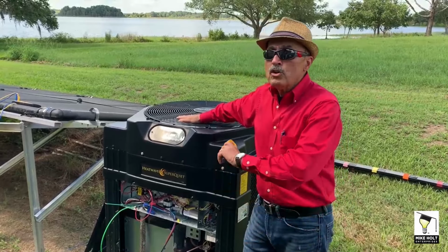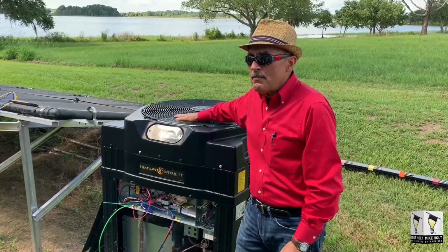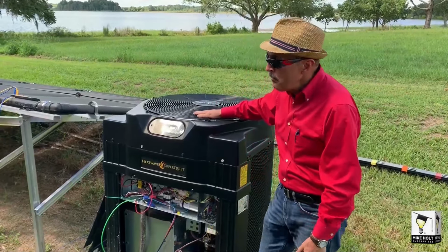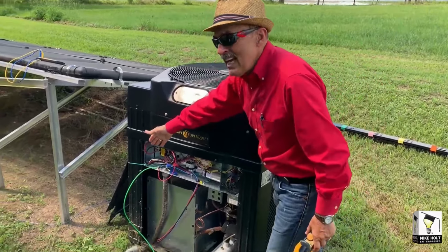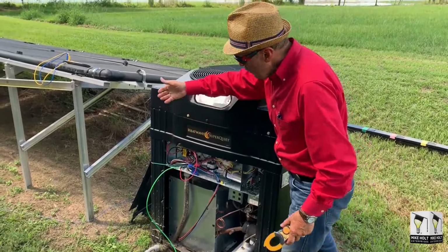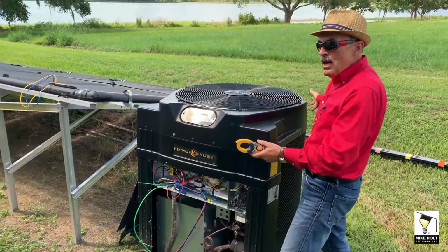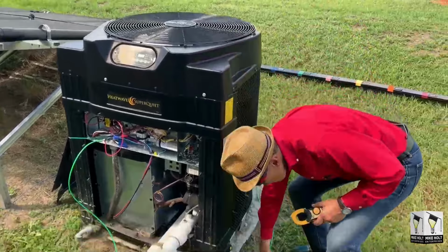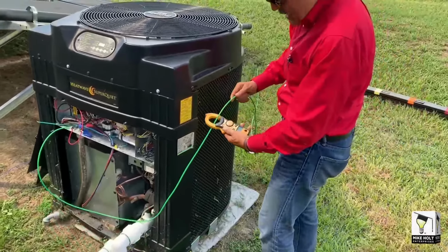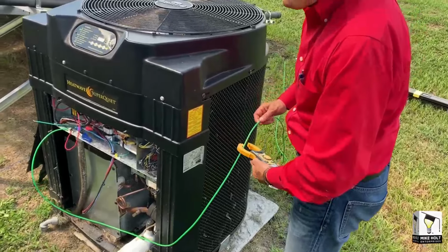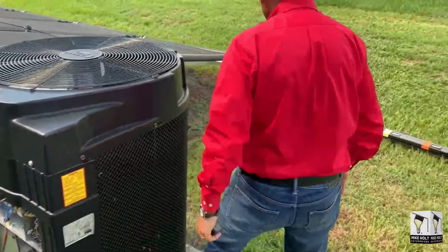One of the reasons why you never want to drive a ground rod to any piece of equipment. Now let's see what happens though. They did not have an effective ground fault current path. They thought, no worries, we'll drive a ground rod. We know the current was less than 1 amp, so that's definitely not going to trip a 50 amp breaker. Now look how it happens over here.